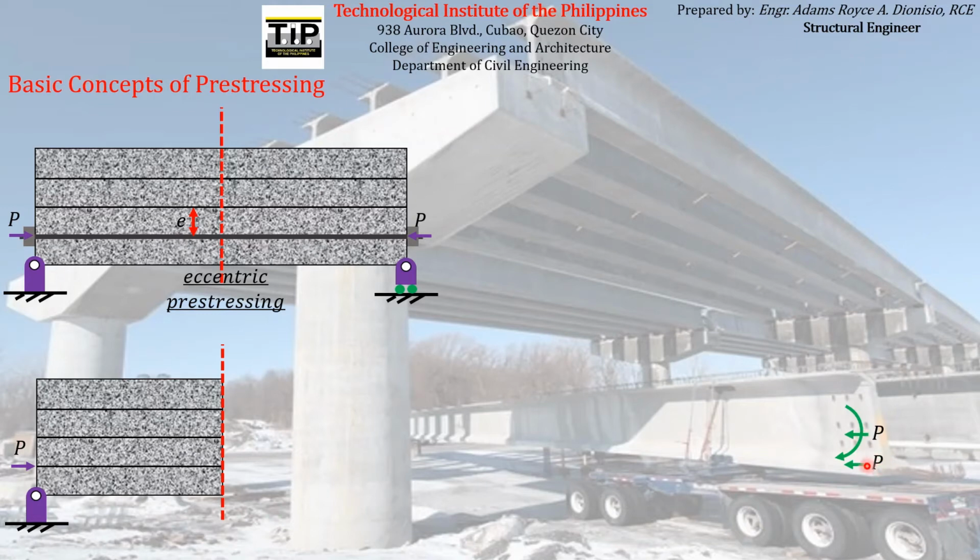If this is the force and the perpendicular distance is equal to E, therefore the moment being produced by this force along this line of action along the centroid of the cross-sectional area is just equal to P times the perpendicular distance, which is E. So the moment will just be equal to P times E. So again, I think we don't need to discuss further this method. We already studied this from statics of rigid bodies, how to move a force from one place to another.